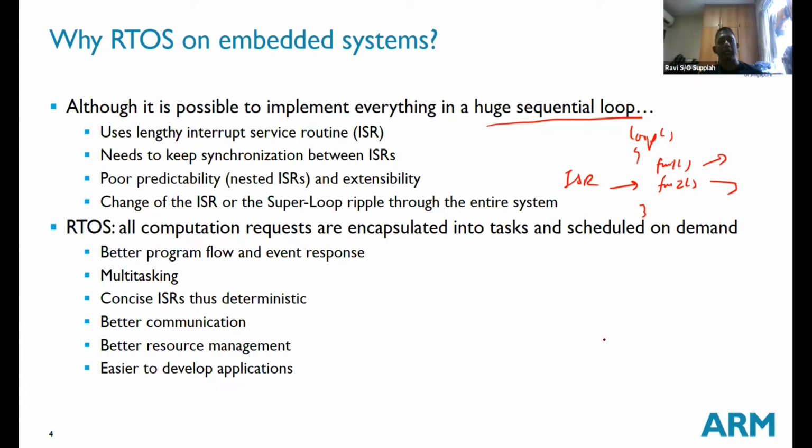Correct. And I would say again and again, do not say the RTOS is the first step in designing an embedded system. If you can go ahead with designing the whole system, fulfilling all the requirements without RTOS, then go ahead and do it. Do not start with RTOS. You think whether you need RTOS first, is it justifiable, and then you decide to switch to RTOS. If you do not need it, you can still go ahead with your loop and your interrupts and so on.